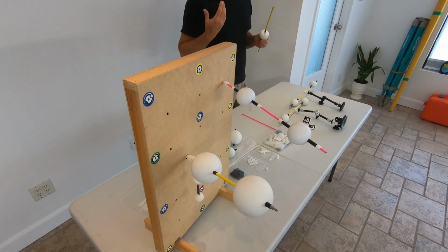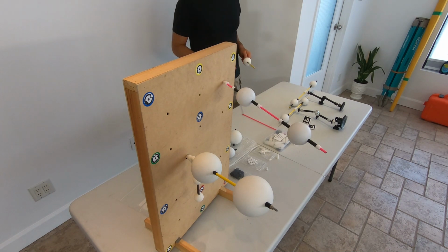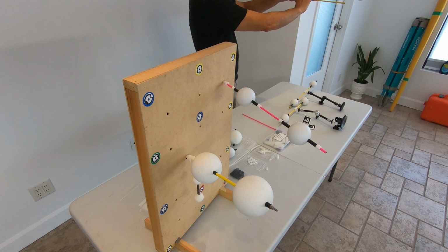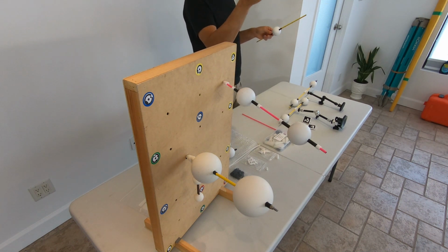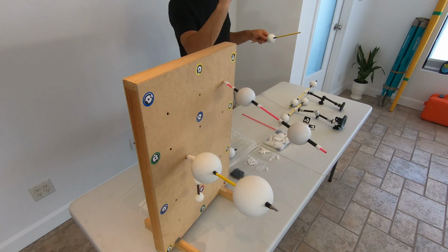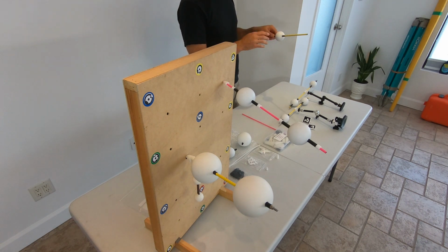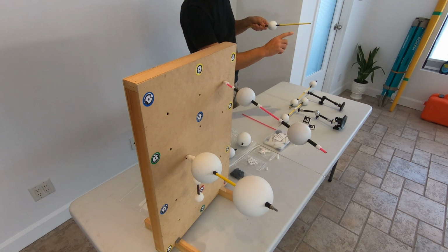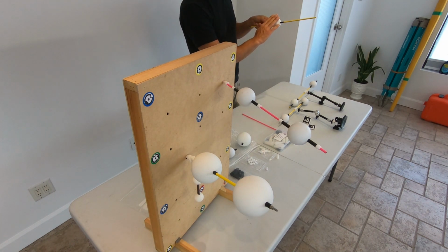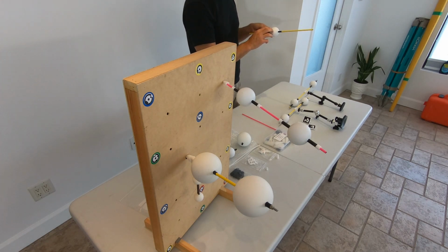Now, what is the benefit of the sphere? Well, in laser scanner software, the sphere is usually a target that's easily detected, and it's also much larger than the rod itself. And the larger the sphere, the greater detection range you're going to have. So you can move farther back and detect the sphere. This is really useful because on the rod, I may only have a few hundred points, if that. But on a sphere like this, at the same density, I could have hundreds or thousands of points, depending on how close I am.